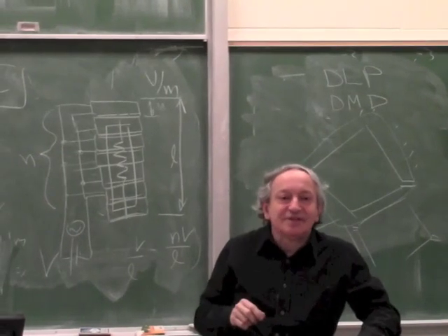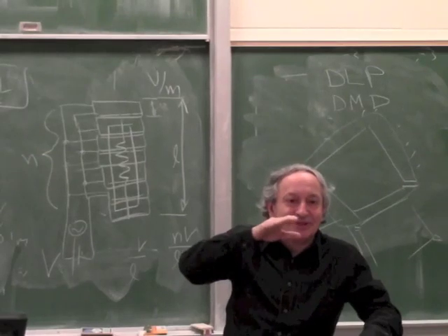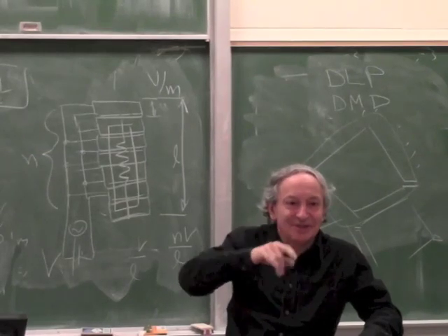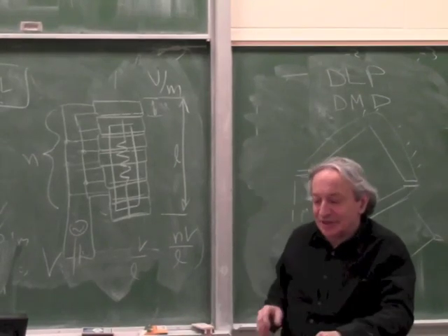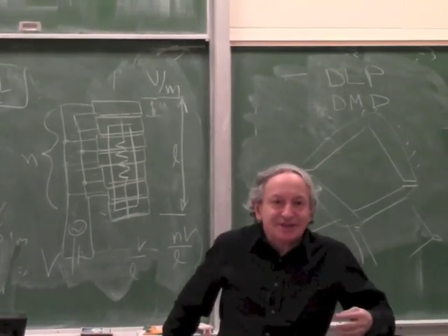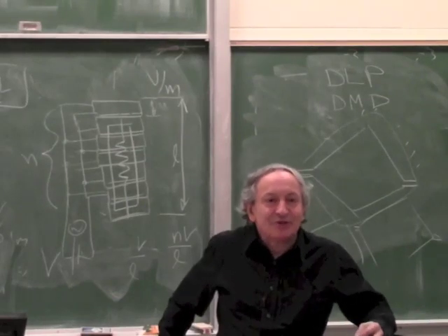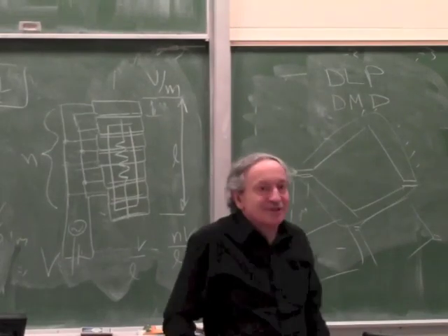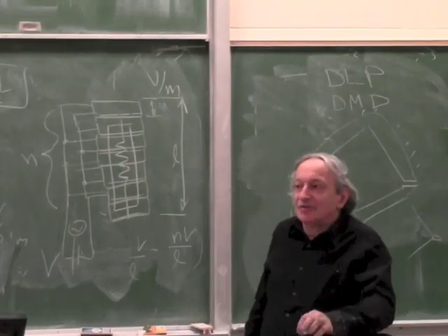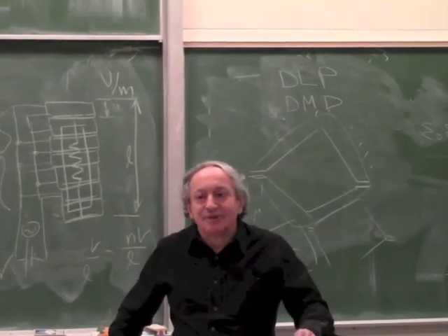So if you have a scanning tunneling microscope where you want to move the needle nanometers or picometers at a time, piezo is very nice. So for very small motions, piezo is very nice, but when you start building a big actuator from piezo, you realize right away it's no better than a magnetic actuator because of all these problems. Okay, we'll cut it off here. I'll do a quick refresher on piezo Thursday and talk about some other actuators.